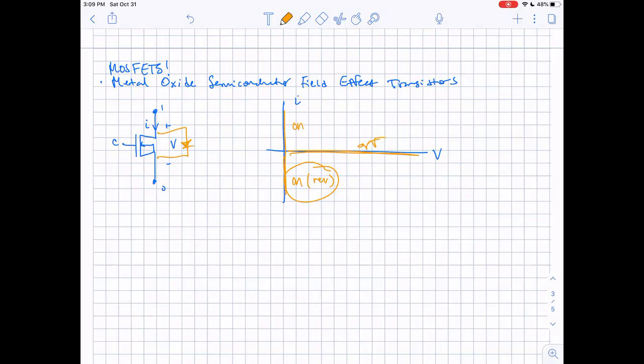So this is essentially a diode in parallel with the MOSFET channel, and that allows it to also conduct a negative current. So this can actually act as a bidirectional device in some applications, even though I defined it as a single quadrant switch. But it's not that efficient because it's a bit slow in the reverse direction. There are a lot of industry applications for this, but I'm not too sure about it.